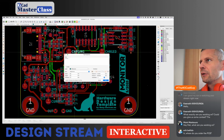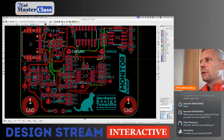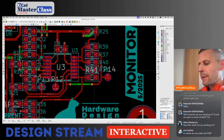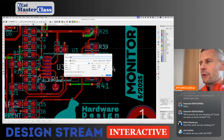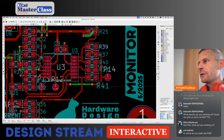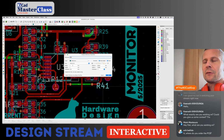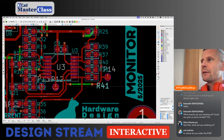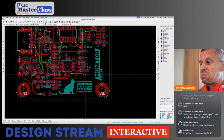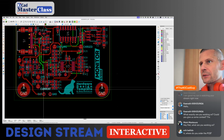Now this is charging. Here is, it may be of your interest. I usually change the size of the labels or reference designators to 0.8 or 0.7. The default value is usually 1 millimeter in all the standard KiCad libraries or in some of my libraries. If I want to align all the labels or